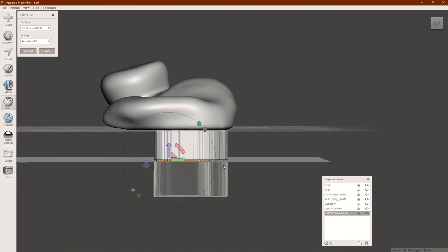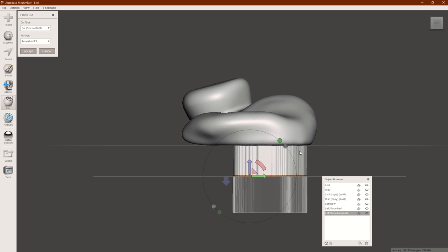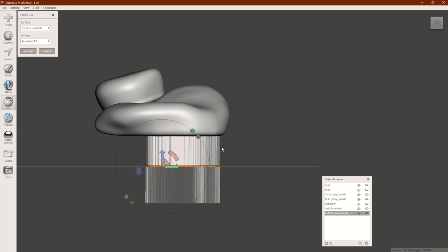Okay, so there's a short way and a long way that it's going to cut. The short way that it's going to cut, I like to angle it about 7 degrees away from the canal. So to show you what that means, I can do this. Now if I'm up here on these snap angles, these are cool because you can get an exact angle. But if I don't want it to be exact, I just move away from them. And because it's on by 5, and I'm looking for about a 7, I'm going to go outside of that. Okay, 7-ish. Right there. 7.04 is pretty darn close.